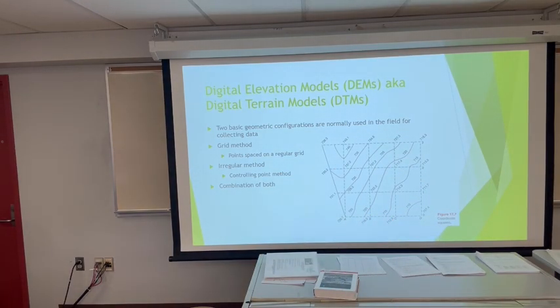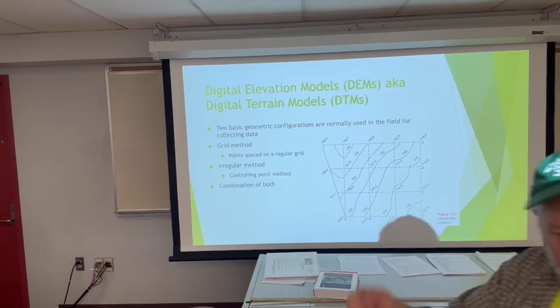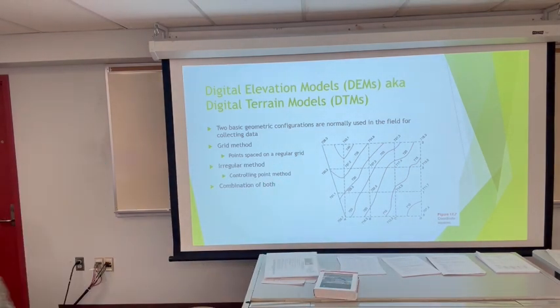Go however far I need to. Walk over 50 feet, get an elevation shot, and start working back that line every 50 feet, if that's the interval that they are looking for. Then likewise, if there are some high spots, low spots that need to be defined better, you need to pick that up. And break lines.